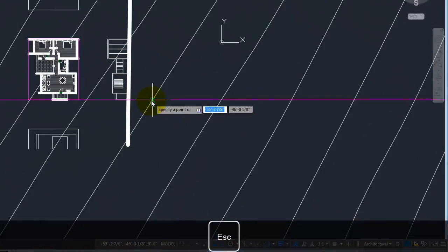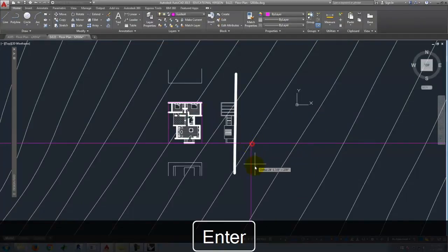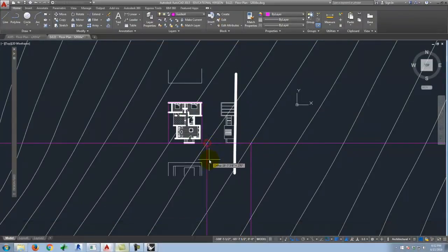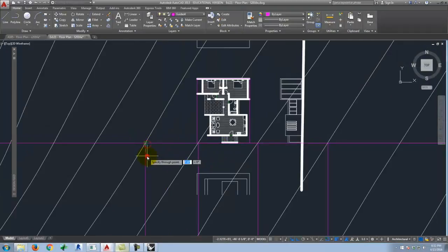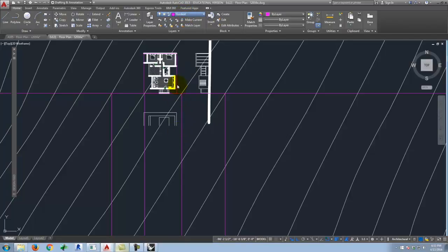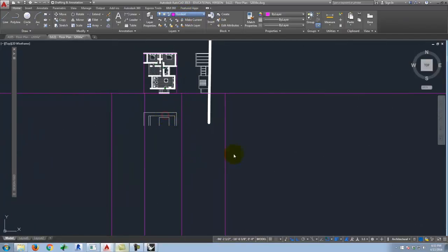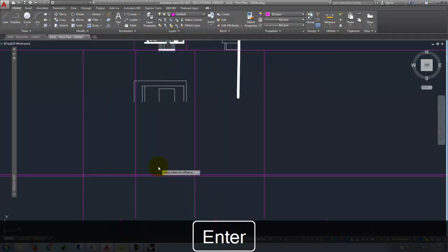So we'll go, let me do a ray right there, right there, right there, and right there. So again, I have to do it from at least 4 of the contours. And now we'll turn back off the contours. And I'll do the same thing. So an X line somewhere down here, going off in that direction. Then I'll offset the X line by 1 foot. There.